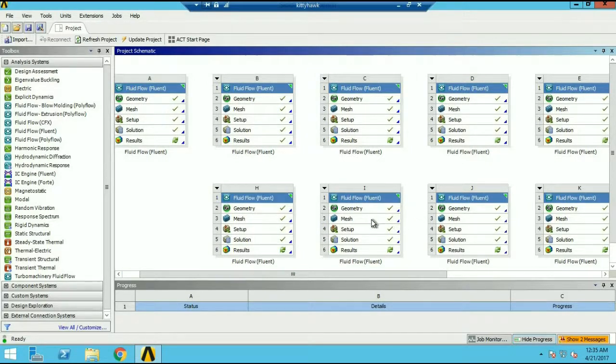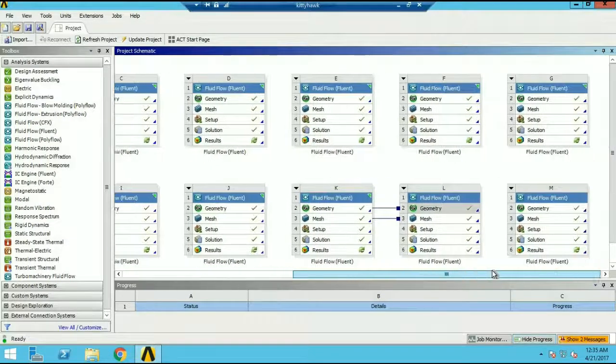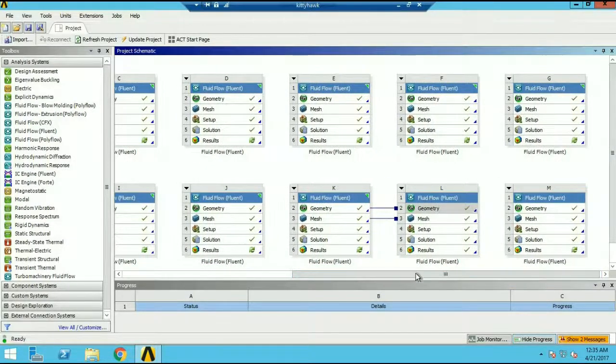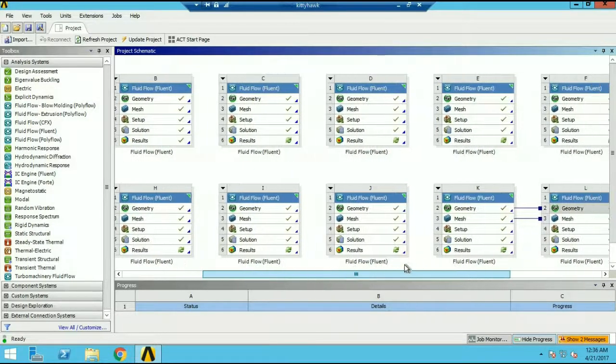Sometimes it would fail. So again, just increase the quality of the mesh, so make it fine. A few of them I had to set to tetrahedron, especially towards the end at like 12 degrees, and you'll see that later. But yeah, and then just go through and solve it. Took about 7 minutes each, so took quite a while to get one, but the results are worth it.